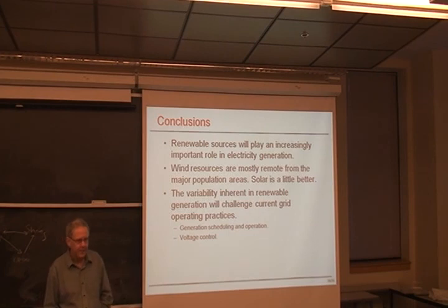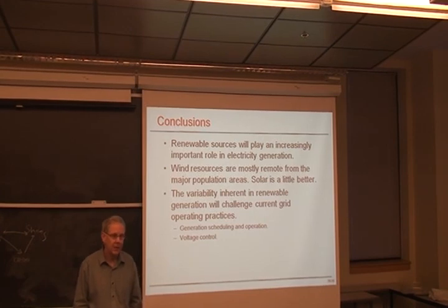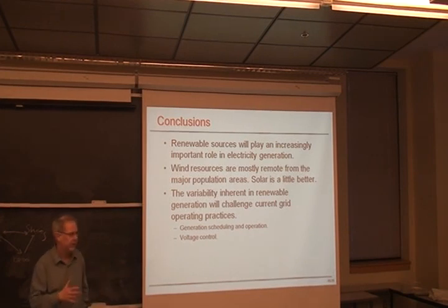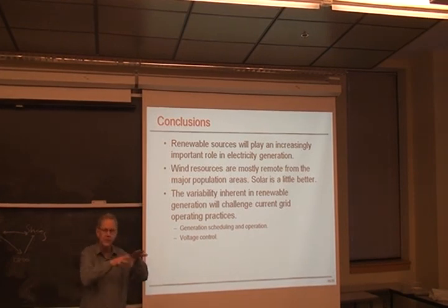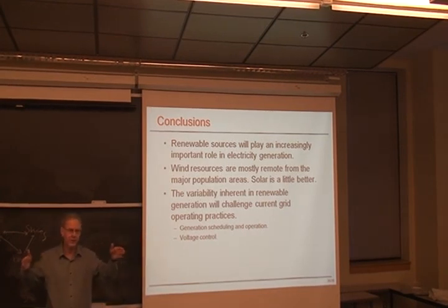Quick question. You mentioned that voltage regulation at wind farms is a bad idea, but that voltage regulation at the solar panel with the inverter is a good idea. How do you reconcile those differences? A wind farm tends to be remote from where the load is. You regulate the voltage at the point where the power is being injected, but you're injecting a variable amount of power, so the voltage drop across the interconnection changes as the power flow changes.